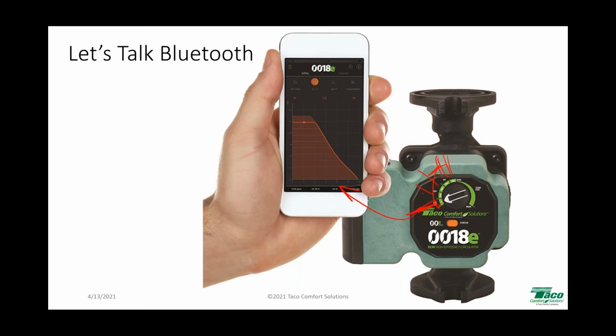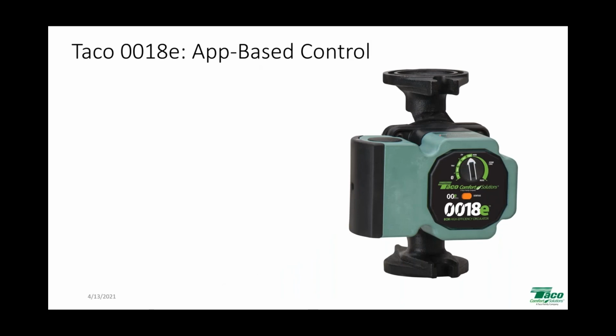When you connect it to the app, you have 9 different constant pressure settings, all right? And you have a multitude of different operating modes as well. So you've got a multifunction. What the 0018E is, it's a multifunction delta P pump, meaning it has proportional pressure for continuous circulation, thermostatic radiator valve type applications for a circulator that size. You have constant pressure, which is your zone valve setup, and then you have infinitely adjustable fixed speed, which you can use to your advantage in a zone pumping situation.